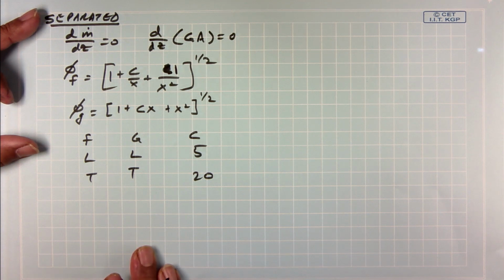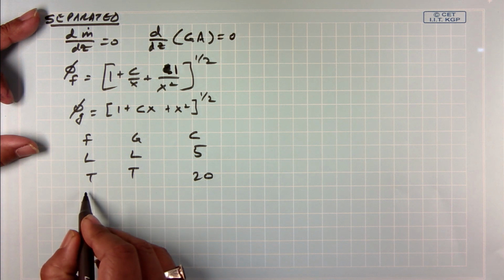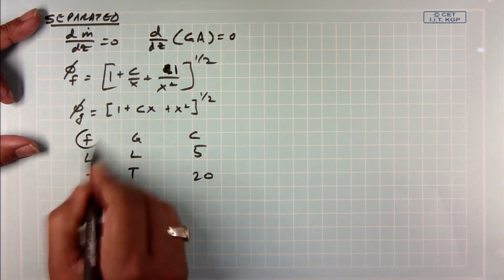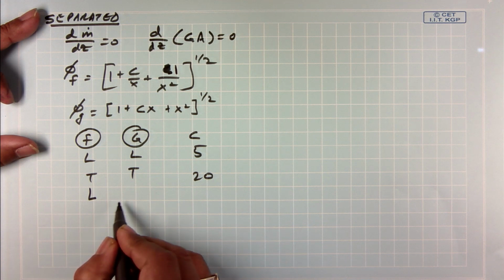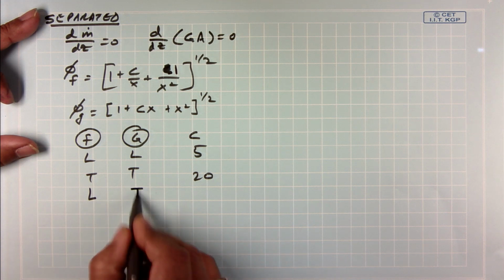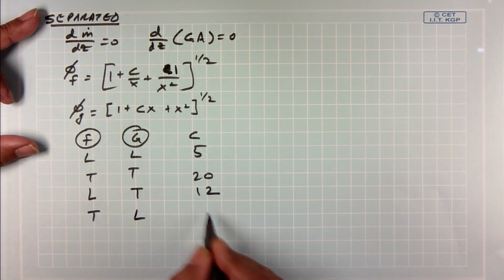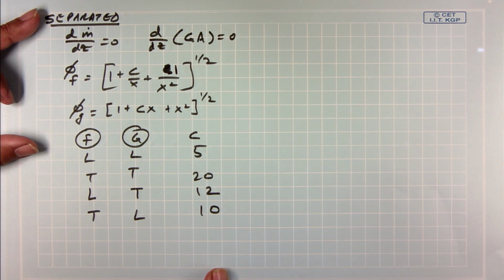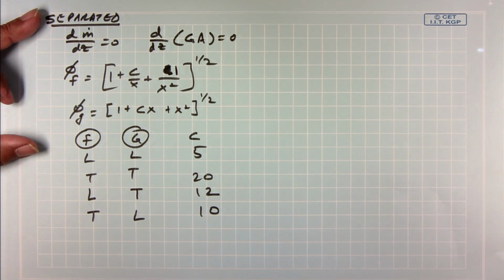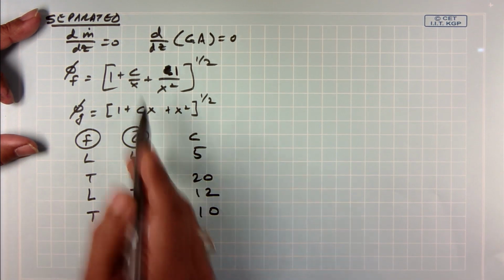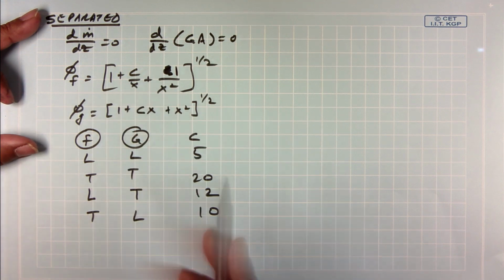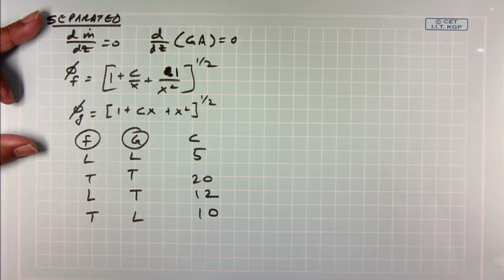Okay. And when the liquid phase is laminar and the gas phase is turbulent, this becomes 12, and then when this is turbulent and this is laminar, this is about 10. Okay. So, this was what was proposed by Martinelli, but there are other flavors of this same correlation, where other people put different values of these constants for different regimes. Okay. But this is actually a good enough approximation for most cases.